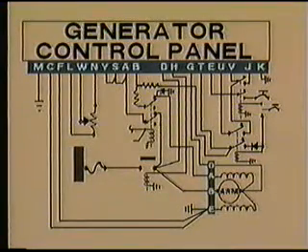Here is a typical write-up. The pilot reported that the left-hand generator would not come on the line. When he moved the generator switch to the reset position, the voltage would climb to 31 volts and then drop back to 0. Have you got any idea what caused it?